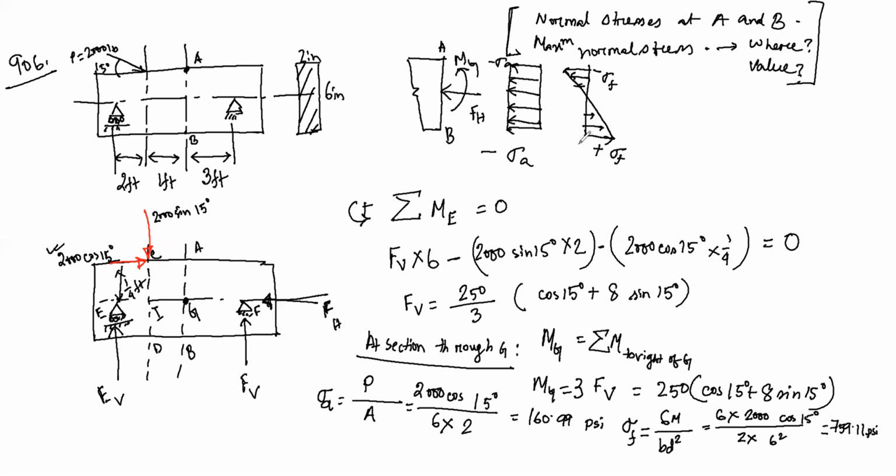So আমি যদি এখন sigma a, that means this one, আমি যদি ফোর্স বের করতে চাই sigma a, এটা হচ্ছে গিয়ে টপ সারফেসের জন্য। সো sigma a যদি আমি বের করতে চাই তাহলে কি হবে, টপ সারফেসে আমার axial loading is negative, so negative sigma a, এবং ফ্লেক্সারাল লোড নেগেটিভ, সো নেগেটিভ সিগমা এফ। সো যে মানটা আছে 160 759, এই দুটো বসালে আমার আসবে হচ্ছে -920.10 psi,